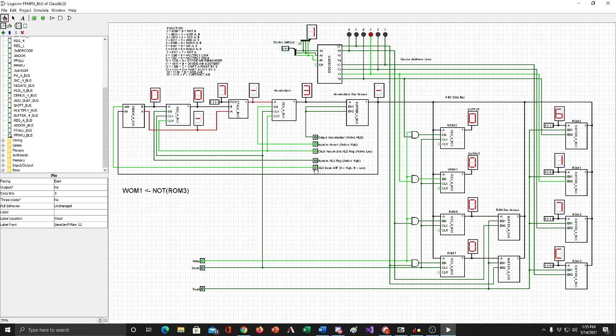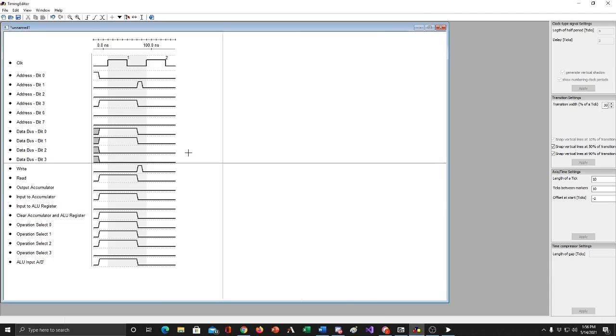So at the moment, it actually doesn't matter which direction this is pointing, because the accumulator has the value that we need to know. So we're not going to change the accumulator, but we are going to output it. And this clear thing needs to stay high, so we'll keep all of that. So the clear, we're not going to clear it at all, so I'm just going to make this high the whole time, this one right here. So we brought the read low, we brought the write high. We need to output the accumulator.